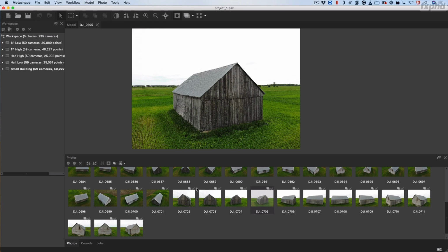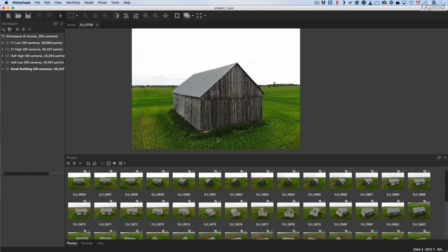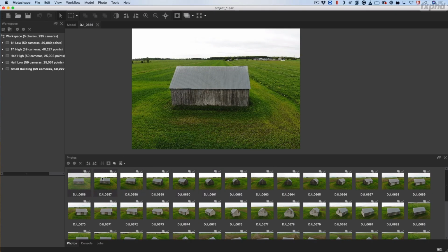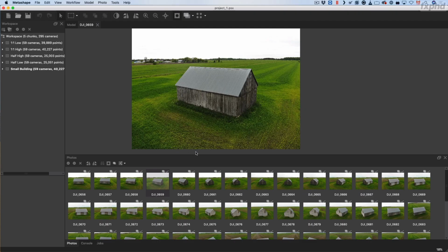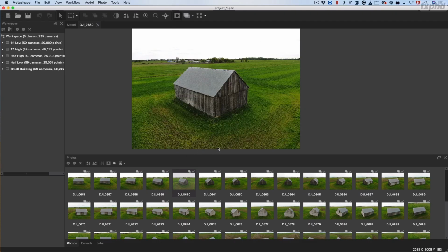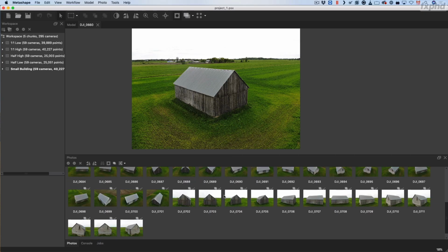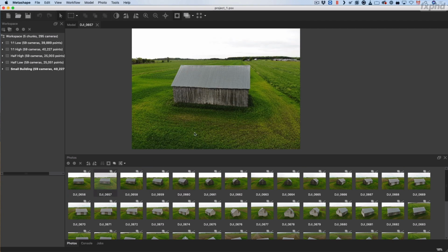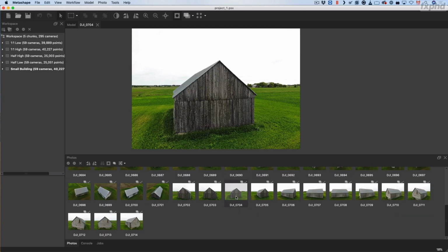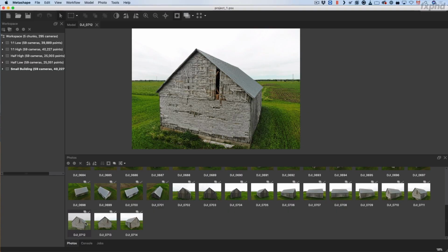So what you really want to make sure is that from one image to the other, you have some overlap so that the software really understands the path of the camera as you were shooting your images. So make sure that you have at least something like 30% of overlap from one image to another. Another important aspect when shooting is to keep your camera movements close one to another. So you don't want to take a picture of, let's say, a wall of the building, then go to the completely opposite side, take a picture, then go maybe on the roof.